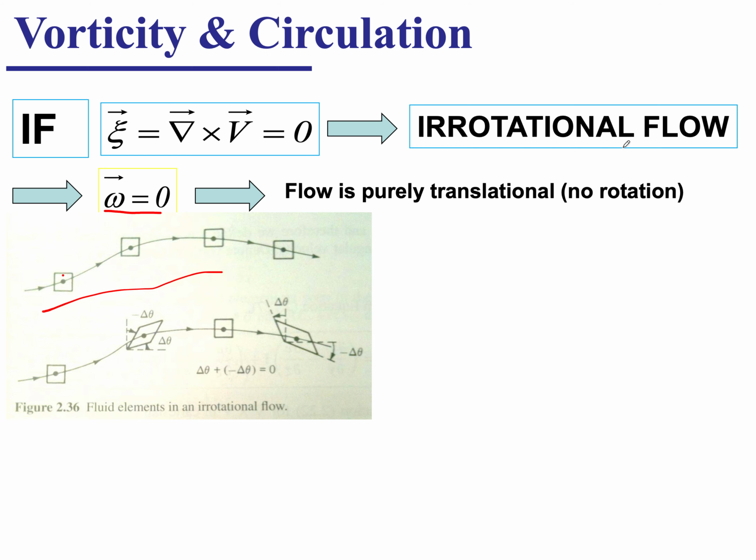And I think we mentioned this in the past, where we're going to break our flow into the boundary layer, where we have a lot of rotation and a lot of effect of viscosity. Sorry about that, I touched the wrong button. So we have a boundary layer and a flow outside the boundary layer. This irrotational flow exists outside the boundary layer, far away from the wall of the airfoil or whatever aerodynamic object we are dealing with.